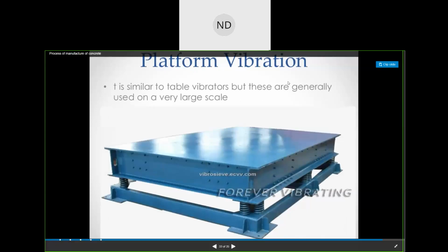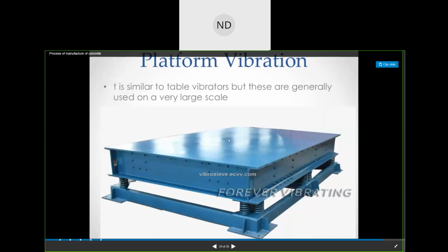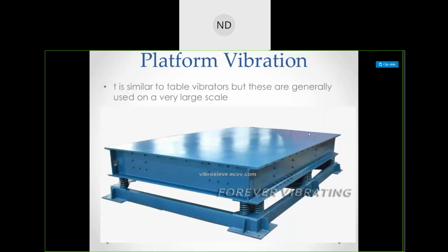Another one is platform vibration, which is similar to table vibration, but it is for large construction, on a large scale. When our work is on a large scale, we use these platform vibrators. Like, suppose we want ready-made slabs, so in a huge member, we can use this platform vibrator for our compaction purpose.